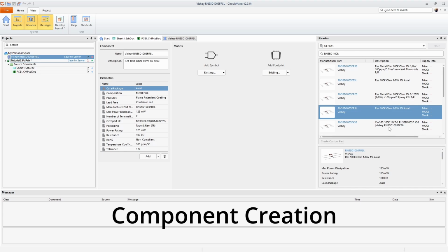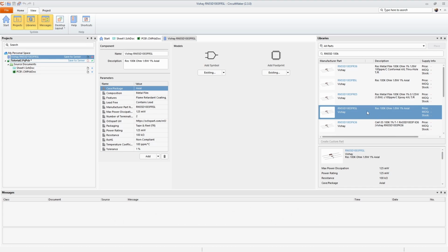So now that you've selected a component, you're going to, just like I did, right click and click on Create New Component, and that will open the component up in a tab just like this. And assuming no one has worked on this component before, you will see Add Symbol and Add Footprint. If you see basically anything else right here, then it probably means someone else has worked on that component before. And you are welcome to keep following my advice here and edit that component and improve it, or you can close it out and open up a different one.